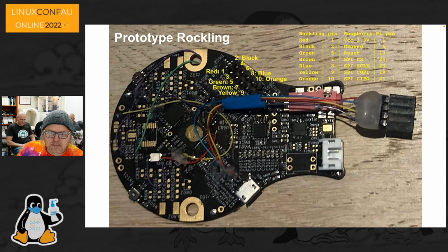And then from there, with Andrew Nielsen's layout and Bob's electronics design, we produced the first prototype, and it was a challenge getting that up. Unlike when you put a CPU down on a board, which usually has an internal clock, or if you apply a clock signal it pretty much works right away or is easy to diagnose, one of our first problems was that we mistakenly chose the wrong internal global system clock pin to use, and nothing worked.